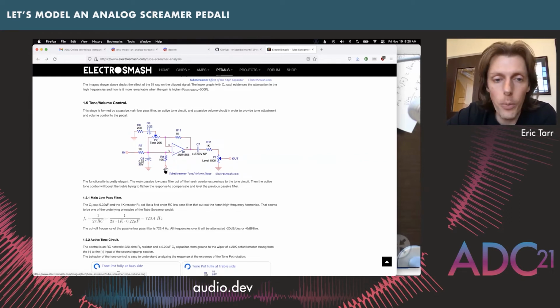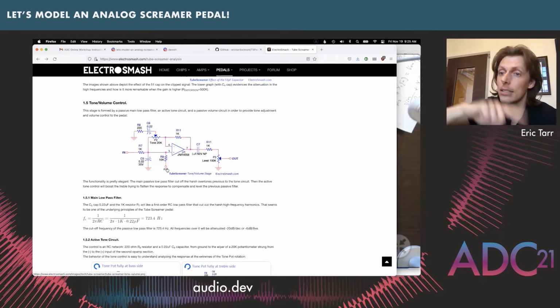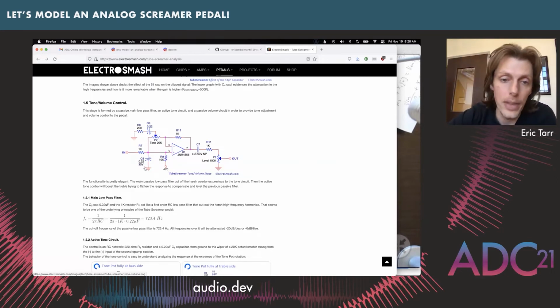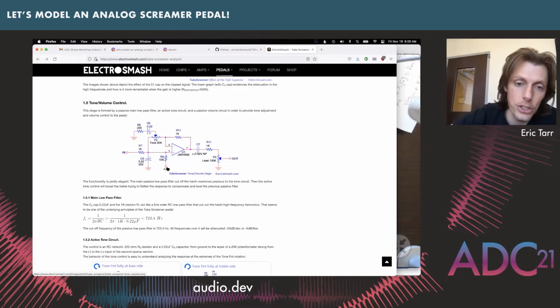So this 4.5 volts as part of the circuit performs a DC offset to essentially take our input signal that was oscillating around 0 and move it up so that it's oscillating around 4.5 volts. That's because we're going to supply a battery to this op-amp, and so that's the range that it wants to go over. Well, what we're going to do is just ignore that, for better or for worse. We don't have to, but we could. We can ignore it, and it works out okay for the tone section.